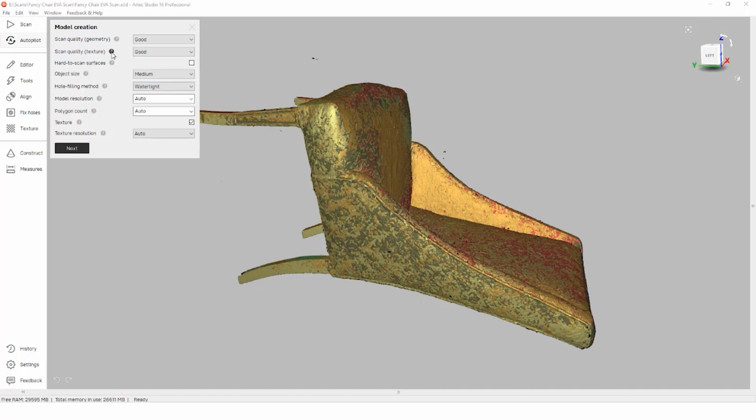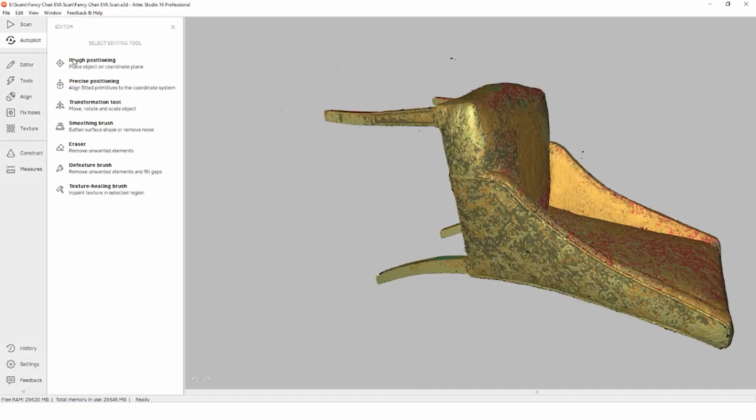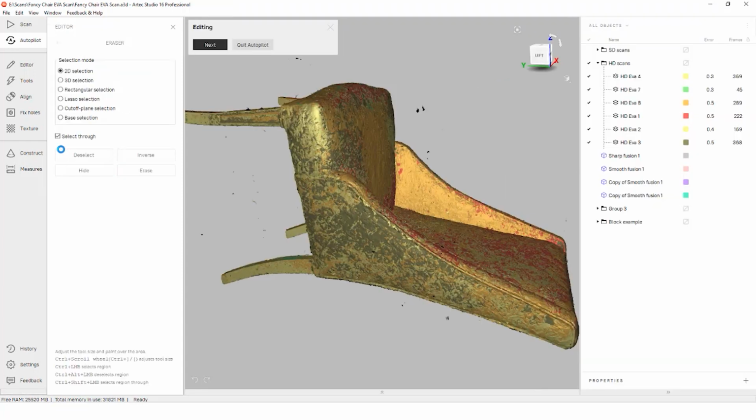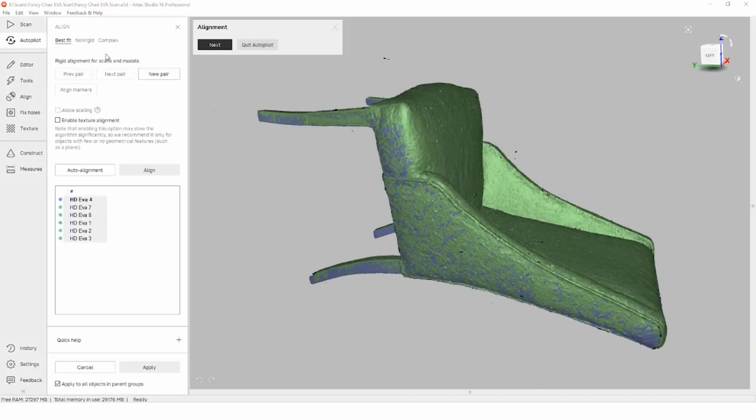To recap the entire process, we first captured our data using the scanner connected to our computer, or we can import the scan data into Artec Studio for cases like the Leo and Ray. With our scans inside the software, we can then clean them by erasing background data and misaligned frames. After the data has been cleaned, we went into the Align tab and did a best fit alignment of our scans together. With the alignment done, we can go into the Tools tab and run a global registration to align the frames of our scans, outlier removal to remove any potential noise data, and then last, the fusion command to create our mesh. This is the general workflow for processing data inside of Artec Studio and can be pretty automated using the Auto tab within the Tools or Auto Alignment.